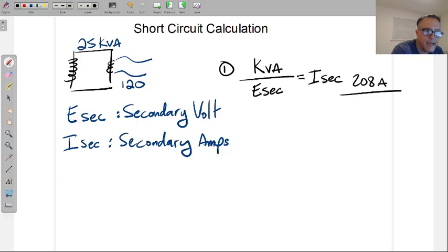So on the secondary side, potential, this is nominal, meaning we've only done this in calculation form. Will this house have 25,000 watts? No way. This house is going to have only a couple of things on during the day. Just like a 200 amp breaker for the house, you measure the breaker, the phases, you're not going to have 200 amps or anywhere near it. You might have 80 at most during the normal process of the house, because the oven's not on while the air conditioner and the dryer and all the lights are on, everything plugged into all the outlets. This is why we do all that derating.